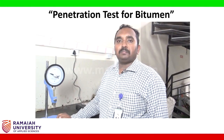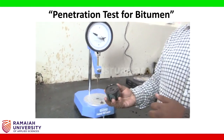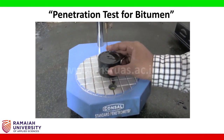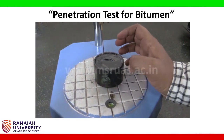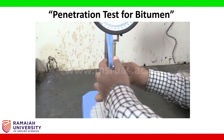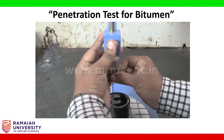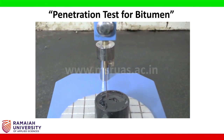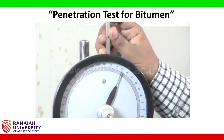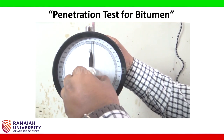Let's start doing the penetration test. After conditioning the samples in air cooling for 1 hour and water cooling for another hour, we are going to place this on the penetrometer. We are going to do some initial adjustment. The first thing, I am going to make sure that the needle just touches the top of the bitumen. The next thing, I am going to bring it down and set this dial to 0.